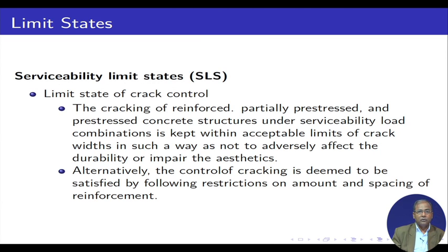Limit state of crack control: the cracking of reinforced, partially pre-stressed and pre-stressed concrete structures under serviceability load is kept within acceptable limits of crack widths in such a way as not to adversely affect the durability or impair the aesthetics. So, not only durability, but also the aesthetics you have to consider. Alternatively, the control of cracking is deemed to be satisfied by following restrictions on amount and spacing of reinforcement. So, that means we can give restrictions on amount and spacing of reinforcement, that also.